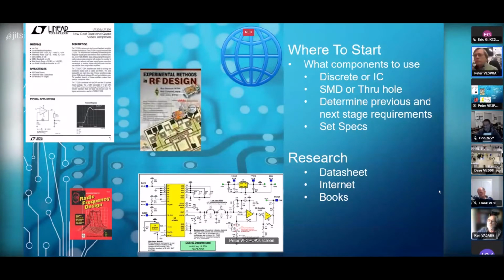In the picture down here, this filter circuit, we use this one in the SNA. And this circuit over here is virtually identical to the LT1253 that Dave and I are working on at the moment. In this case, they're using the AD8008, but it's a direct drop-in with the LT1253.